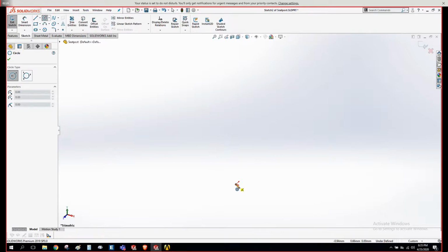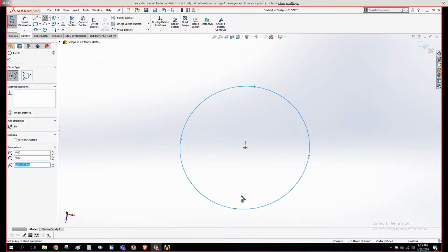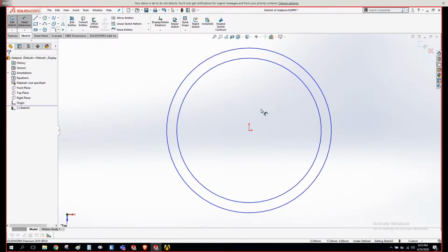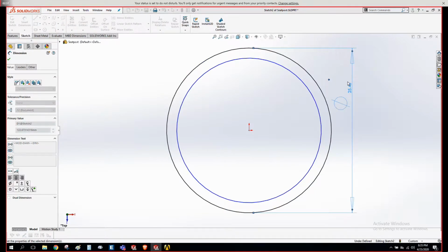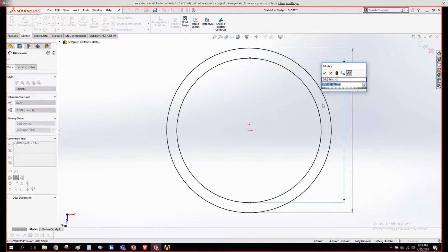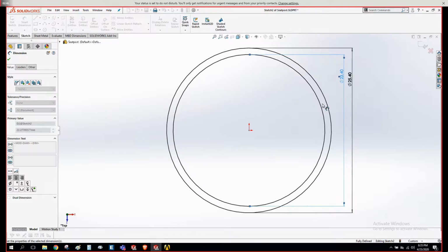All right, so we're going to start with this top plane. There's our outer diameter. Here's our inner, and let's get some dimensions on that. I believe a standard seat post is about 1 inch. I know we're working in metric, I know. And let's go with a 1 millimeter wall thickness, which would give us this as our ID.